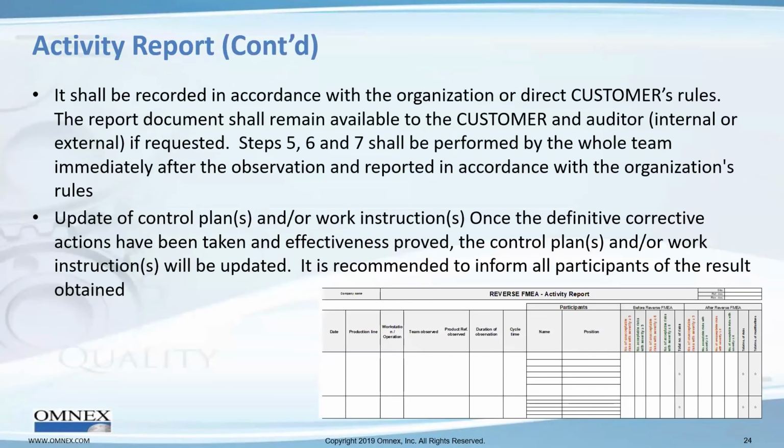And so then we record all of our evidence. And the purpose of doing this is that once we're done with this line that we're doing this full reverse FMEA on, we have all this documentation that we can send to our customer or share with our customer. Maybe there'll be some material you won't want to share with your customer, but we'll have all of these artifacts to show that we actually went through a formal review of all of the activities in the operation, and confirmed that the rankings that we gave them were adequate.